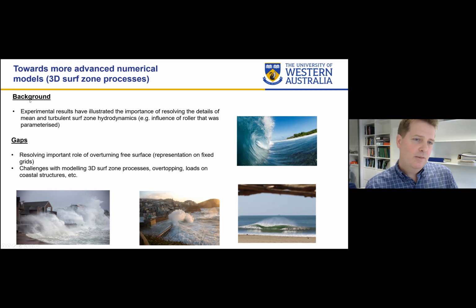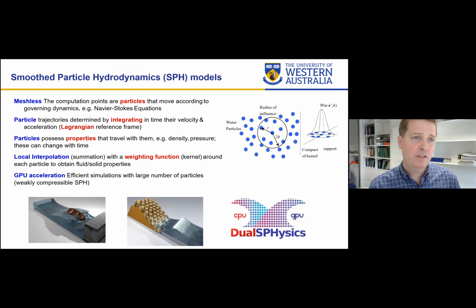And I'll talk about those. One of the advantages with these modeling approaches is they're really effective and efficient at reproducing some of the hydrodynamic processes in the surf zone through plunging waves, and can deal with quite complicated geometries and so on. So this approach is a computational fluid dynamics approach referred to as smooth particle hydrodynamics.